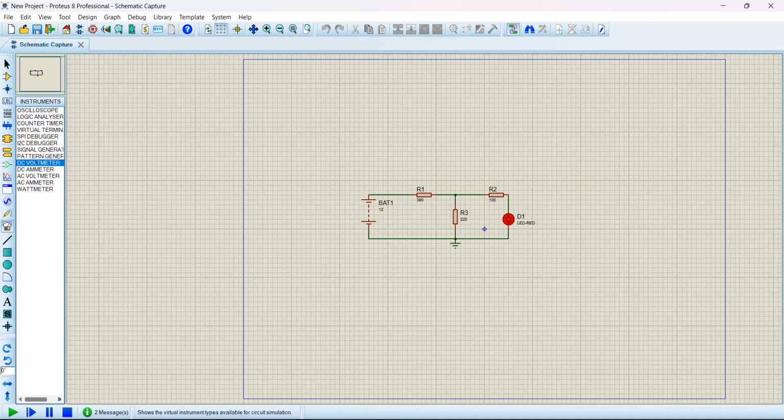Before you place your components, you'll need to stop your circuit. Now my circuit is running. I want to place this voltmeter. You hear the sound? The sound tells you your circuit is running. You can't do fault finding while the circuit is running. That one is for safety. You cannot place a component while you are supplying a circuit, so you might get shocked. I will stop my simulation and then connect my DC voltmeter.